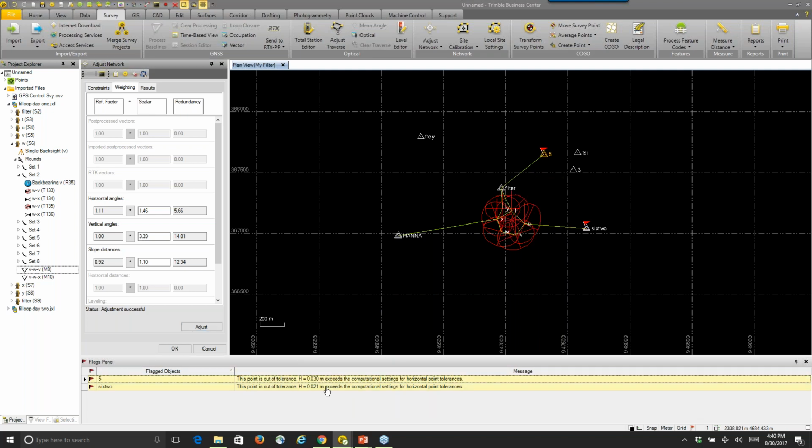points. These 3 millimeters here, if we looked at it, would just say that the least square adjustment differs from the observed information a little bit, slightly, and we know this because we're constraining our network a little more. Maybe our overall network isn't as tight as what we initially thought it was, but now at least our traverse is best fit to our entire network and not just to 2 points.